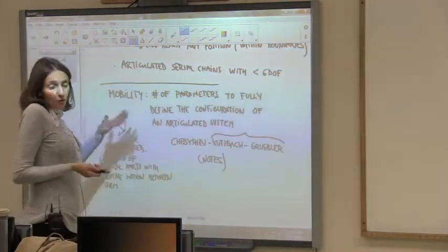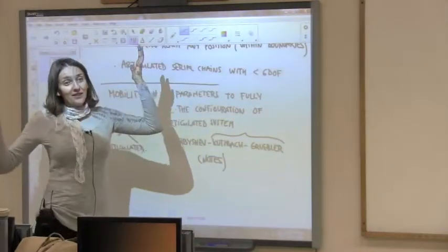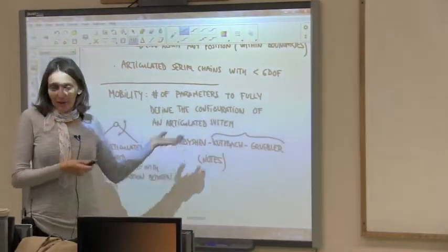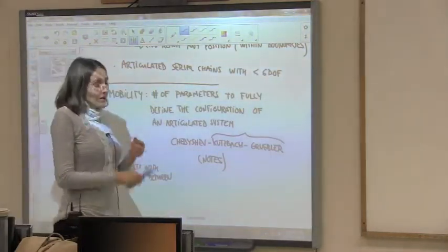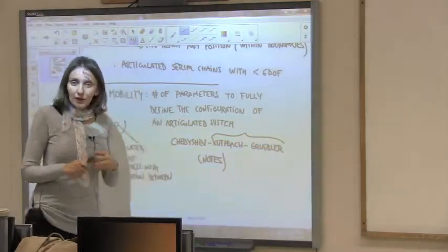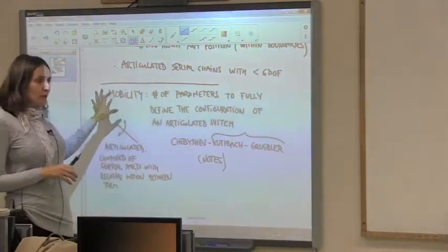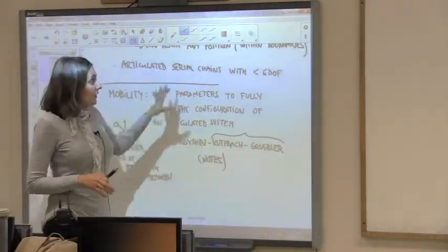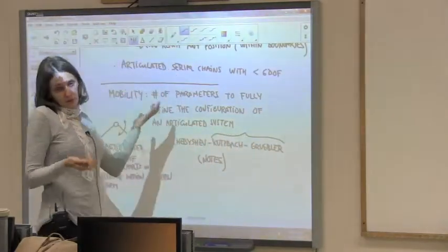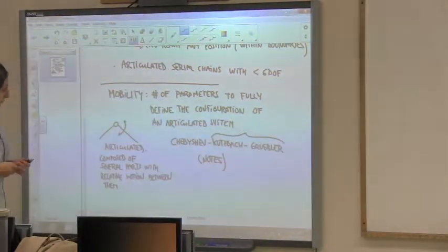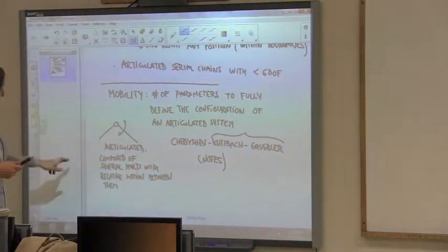You know, an easy solution to the problem would be to just make everything 6 degrees of freedom or more, right? Then you don't have to worry. But that means more complicated architecture, more complicated control. If you are designing for a specific task, you can embed part of that difficulty in your mechanical structure. Okay, and that's basically what this does. All right, so